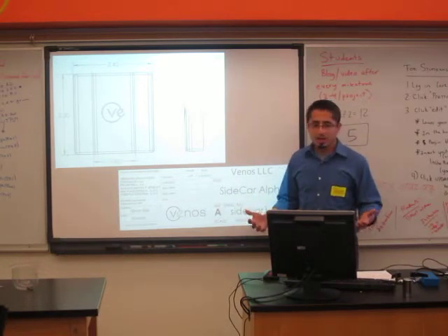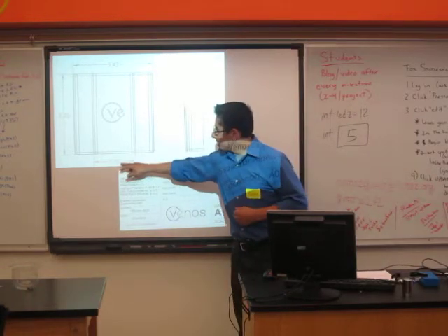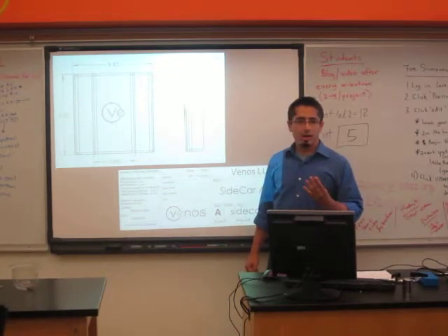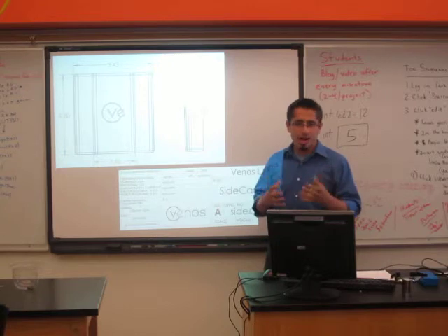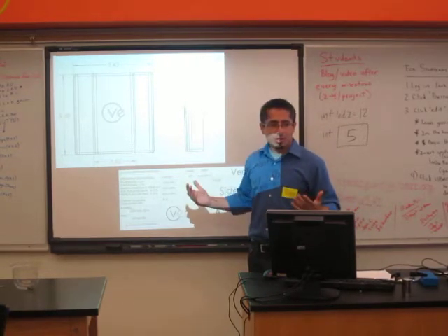It's not too complicated. A lot of times in technical drawings, people will put 1.8200, 4 decimal places. The machinist goes, I cannot hold a 10,000th of an inch, which is like slicing your human hair up many, many times. You just can't hold that cutting metal. It expands, contracts. Cutting wood, not going to happen. So a lot of engineers just go crazy with that.